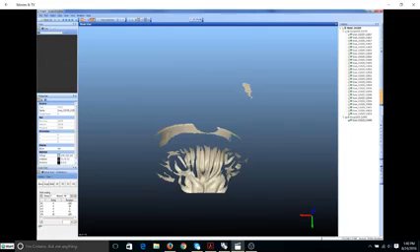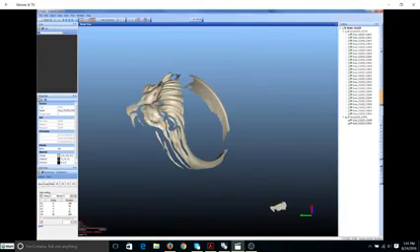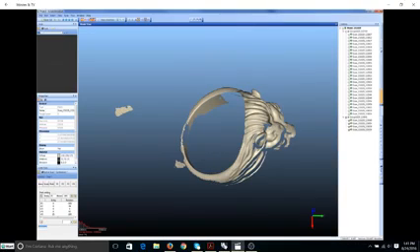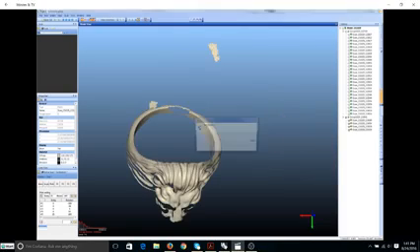That will disappear, and now we were scanning the part in a different orientation, which means that a different area is exposed, and we'll get another set of data which will fill in some of the areas. Once this is done, EasyScan allows you to take those volumes and edit them and then align them into one volume. So in the case of things with pockets or undercuts, you can capture that, but it takes a few scans in order to do that.